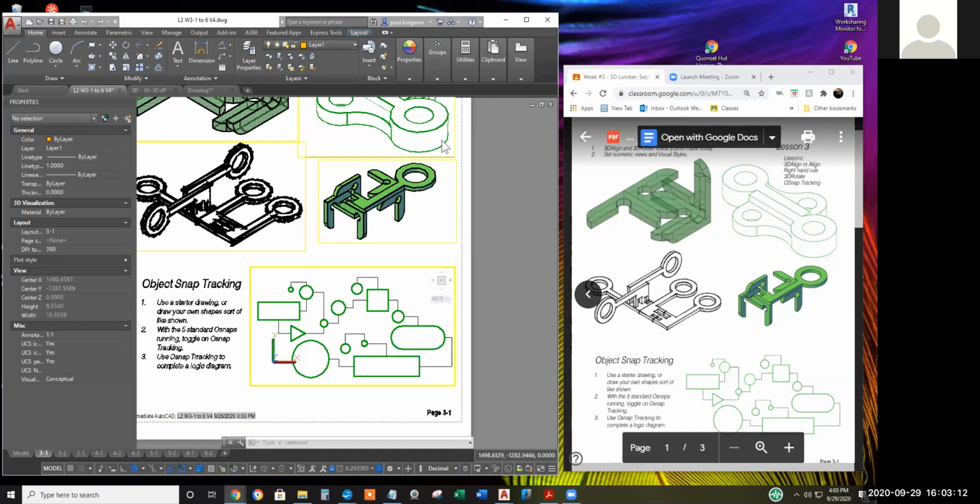Hey, Sally. Interesting, a few students figured out how to subtract the holes out of the 3D solid extrusions. But for good measure, I want to demonstrate the subtract. And a couple students had trouble. They didn't join all the lines and arcs together into a single closed polyline before extruding. And they ended up with cattle fence type surfaces.